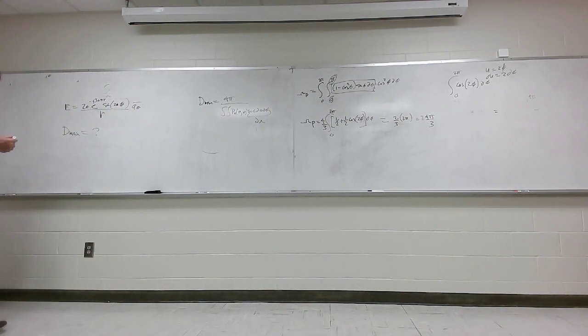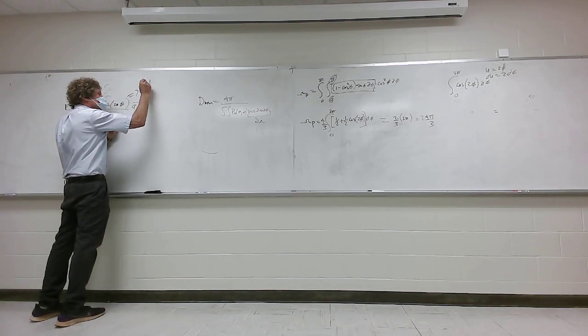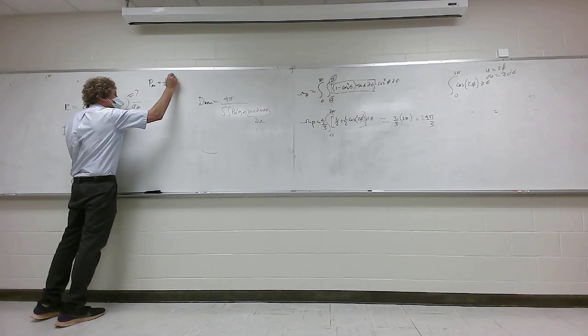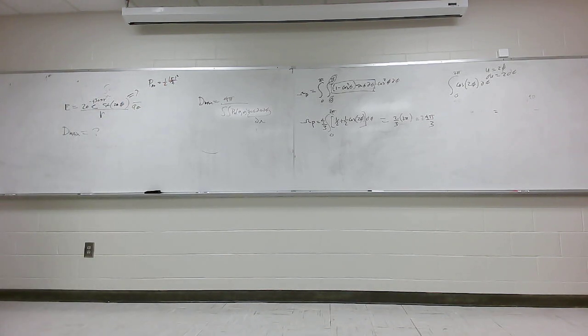So if I wanted the power density from this, then P average, the average power density, would be 1/2 magnitude of E squared over eta, right? Y'all see there would be a sine squared in there, right? Sine squared is something that's not just phi, it's 20 phi, but sine squared nevertheless. Do you all agree with that?